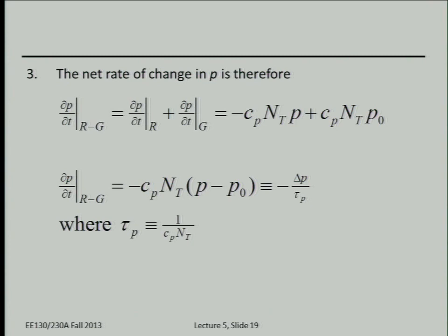So let's look into the non-equilibrium case, where we first turn on the light. Regarding the generation rate, this is the equilibrium case, okay? But what's going to happen here? We're going to have net recombination, right? Because we have too many excess carriers. So that's the definition of the recombination rate introduced by those excess minority carriers, okay?